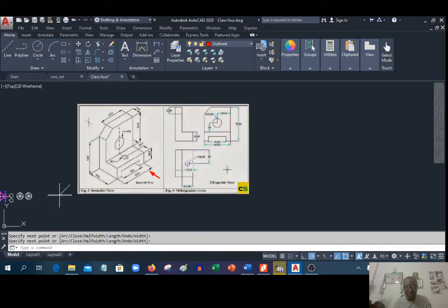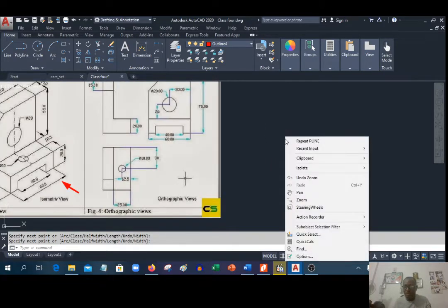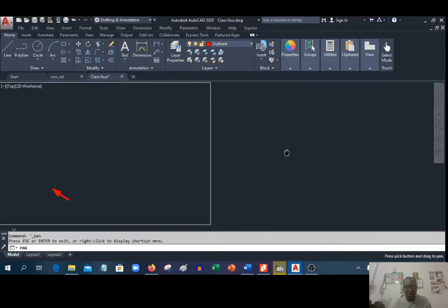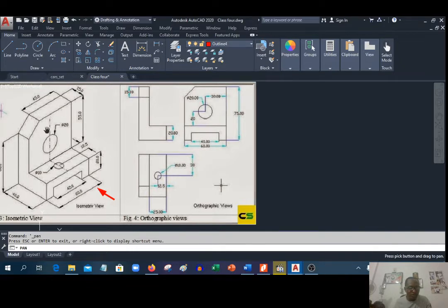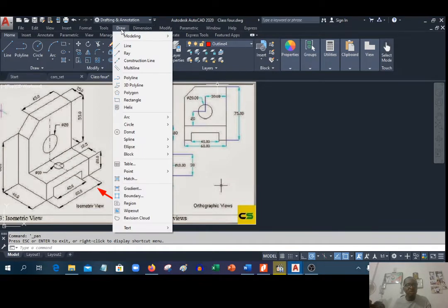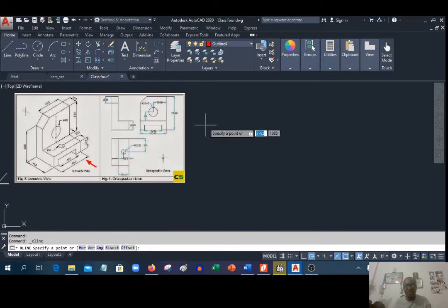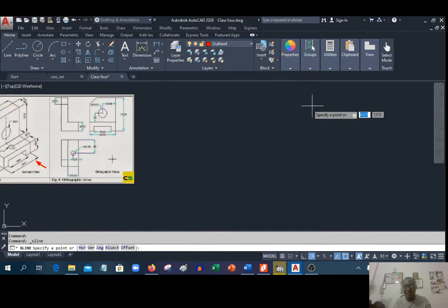So let's just place this by the side while I'll use pan to place it properly. Okay, I actually want to be seeing the dimensions that we have here, right? That's what we're going to use to draw. So maybe we'll come to it from time to time. First, I'm going to use my construction line, vertical, right? I'll type V for vertical. So click, enter.